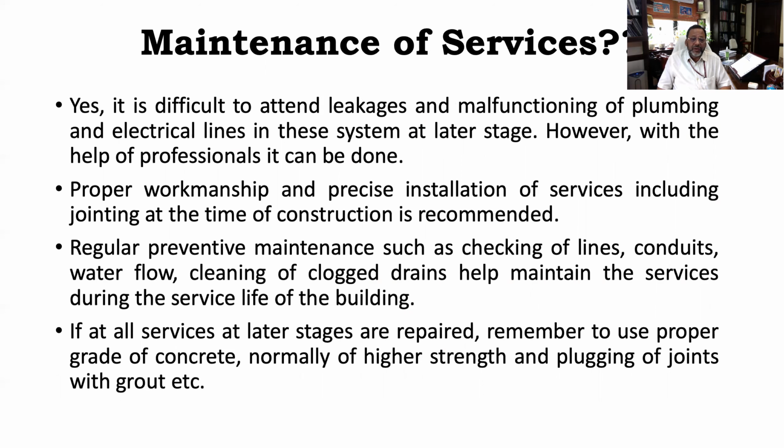We have to clean the clogged drains, and all these things will help maintain the service lines. And nowadays, with modernization and the kind of material and specifications we have, whether it is sewage pipes or UPVC pipelines, if they are properly joined, there are no questions of leakages or malfunctioning at a later stage.